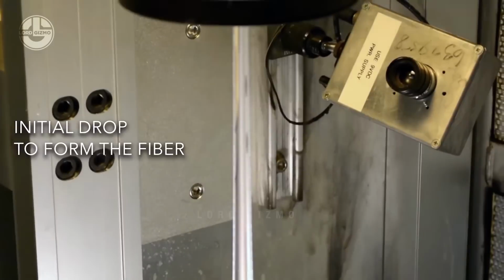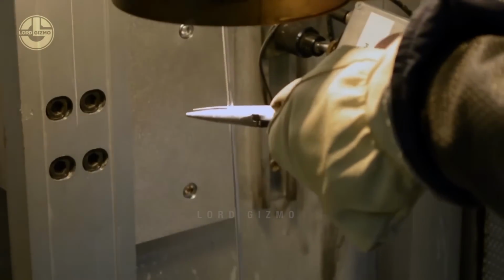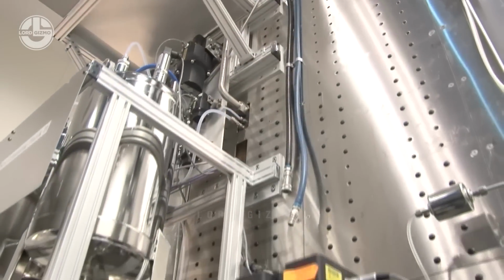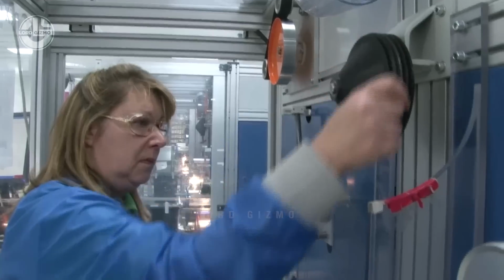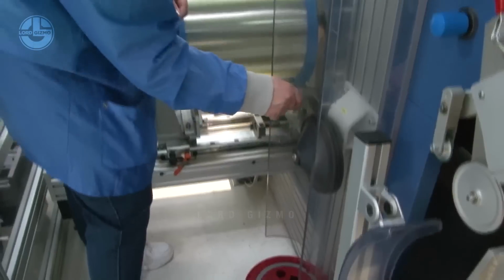A diameter gauge system with laser technology ensures every bit of the optical fiber has the same desired dimensions. The optical fiber is then run through a die, which applies a protective coating to make it resilient and easy to handle. Now, it can be wound on a drum. It passes several tests and trials, such as testing tensile strength, which should be at least 100,000 pounds per square inch, and measuring its loss of optical power, carrying capacity, and numerical aperture.